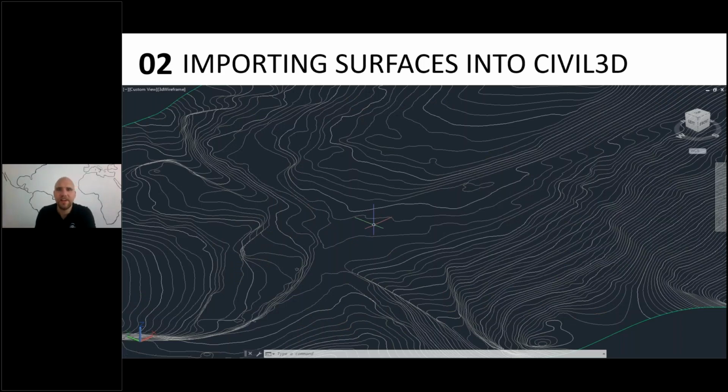Okay, now the second part of the demonstration. So we checked how we can bring in the point clouds, and this goes for Civil 3D. I think ZWCAD also supports import of RCS files, so in that case, the same workflow will apply. You can get the ReCap, convert those LAS files into RCS format, and then load them in.